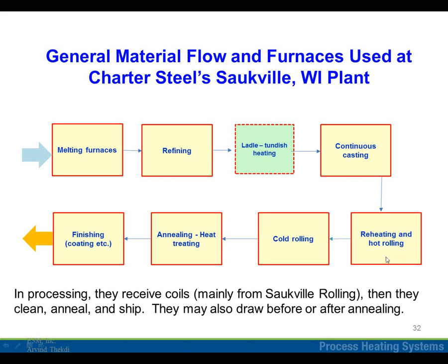Reheating obviously is one big one. Not much energy used in cold rolling, lots of energy used in annealing and heat treating, and some of them may be in the finishing operation. So we will mark up each one of these, and then between David and Terry, we have made some decisions on what kind of equipment we are going to use for making measurements.